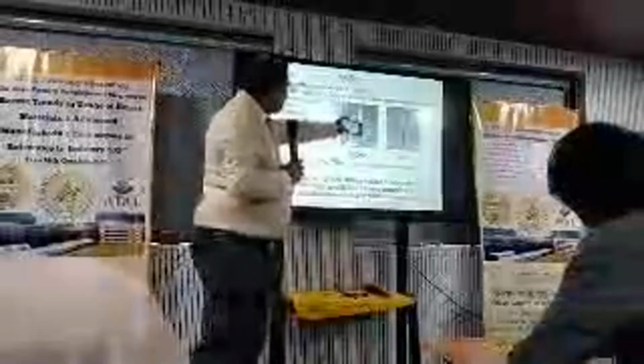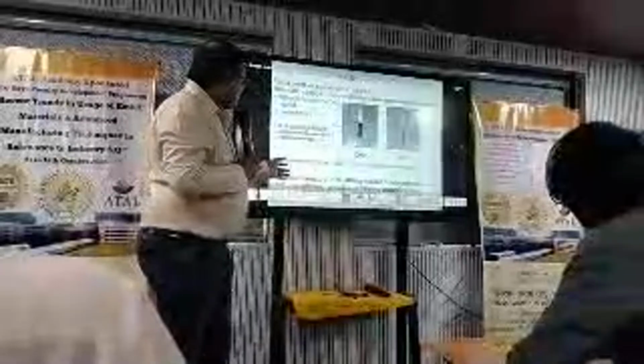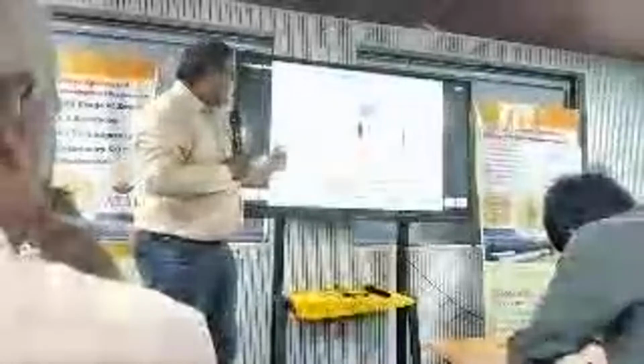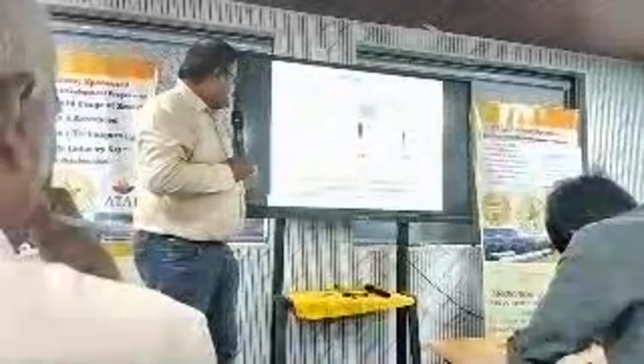It consists of some fluid containing iron particles and suspended molecules. So mainly it is rheology. The rheology of the fluid will be changed by application of the magnetic field or the electric field. That is the main aim. It is an electro-rheological fluid, and if you change the voltage across the electrodes, then the viscosity of the fluid will change. The fluid mainly consists of iron particles in a suspended liquid: mineral oils, synthetic oil, water, vapor. This will be a combination of these.